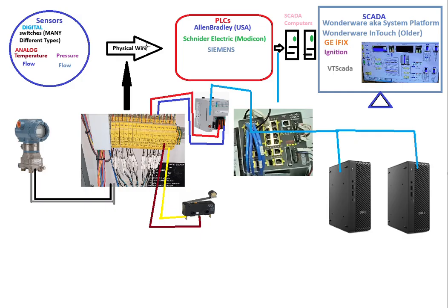That's physically wired to the PLCs, in the US often Allen Bradley, sometimes Schneider Electric, which used to be Modicon and Telemecanique. They've acquired a bunch of companies. Or Siemens, which I haven't worked with very much. And there's like 100 other types of PLCs. Those connect over Ethernet or serial, but most of the time Ethernet over a standard network to SCADA computers.